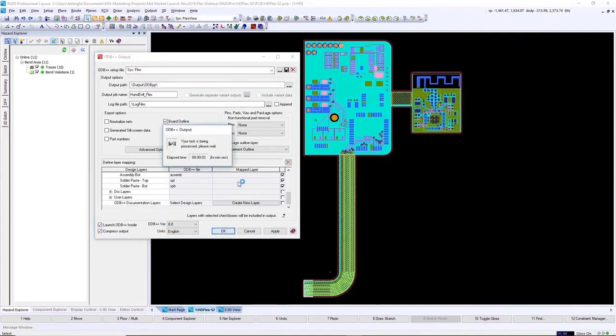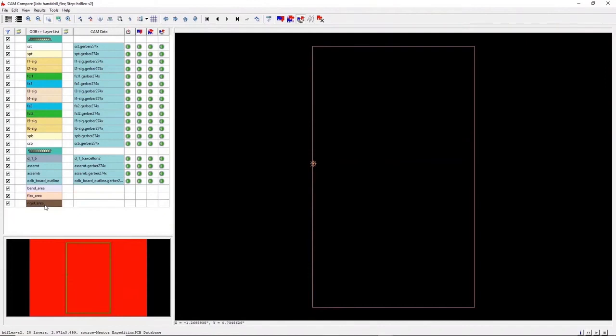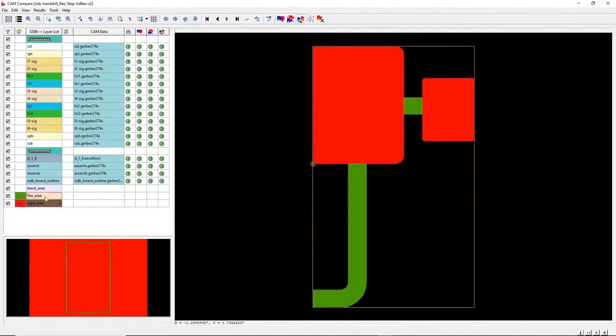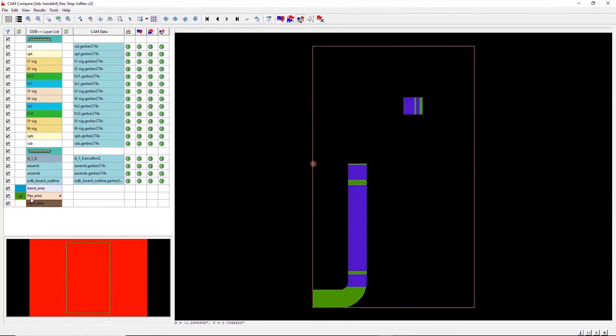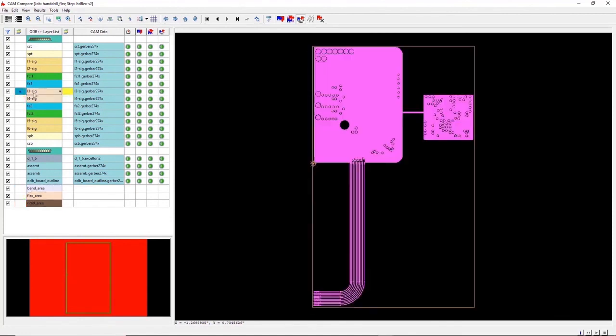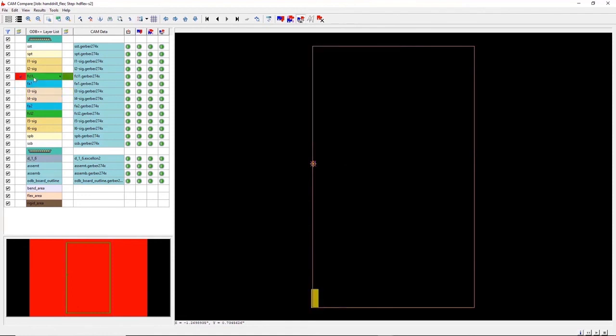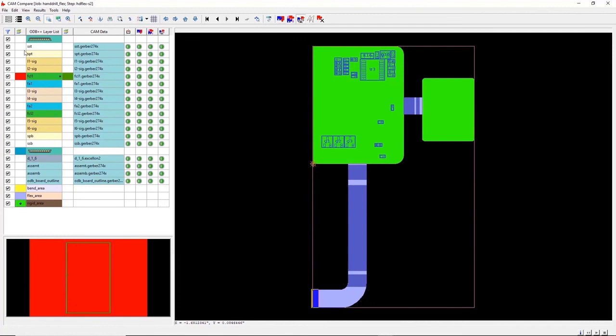So using manufacturing automation, we can set up our ODB++ output. We can save that off into a configuration and reuse it over again. PADS Professional includes an ODB++ viewer. So when done processing the data, it will automatically open the design in the viewer, where you can do last visualization checks on all of the content being included in the manufacturing output to ensure you're providing all the information needed for fabrication and assembly.